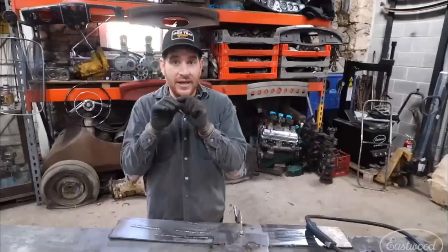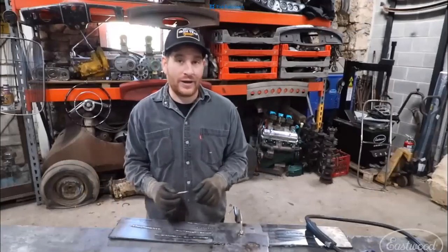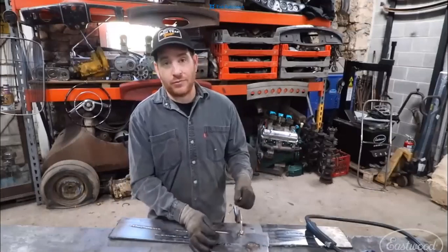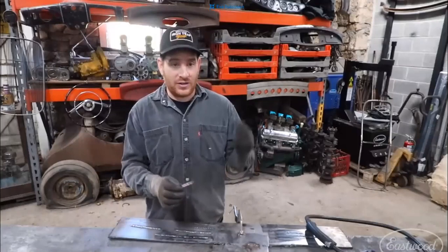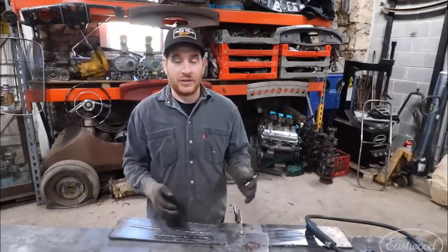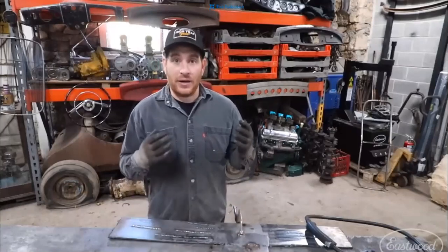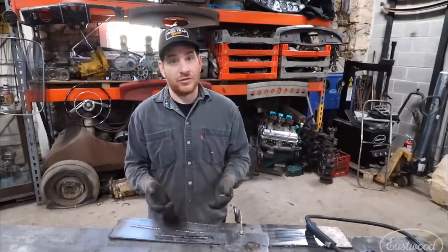Instead of trying to cut a sliver of metal and fit it in there, you can use a piece of TIG filler wire as your filler material, MIG right on top of it. It will burn the filler wire into the weld as well as your MIG wire. It will fill it up and save you from having to cut the panel apart and redo it. But usually between those things, that's what your problem is, aside from just having your settings incorrect.